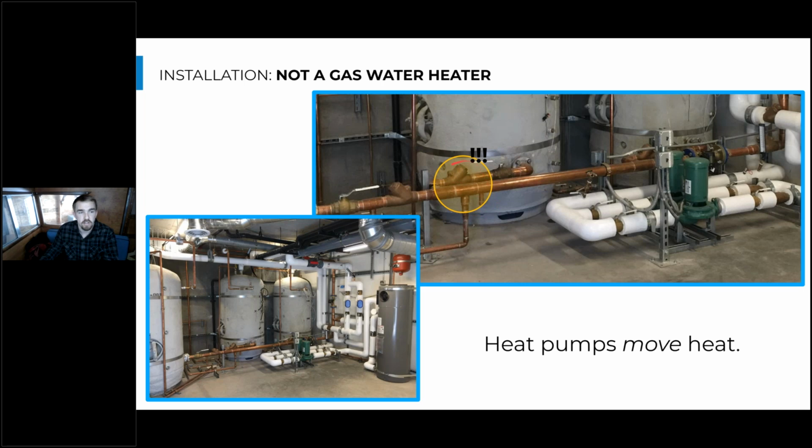So if you were to put a check valve on this line, as plumbers normally do on the inlet of a tank, now that heat pump can't pull that water out, and it's not going to be able to rush water through its heat exchanger and get rid of that heat. So the heat pump's just going to go into alarm and say something's wrong here, because this check valve that wasn't actually on the drawings has been added by the installer as a best practice.